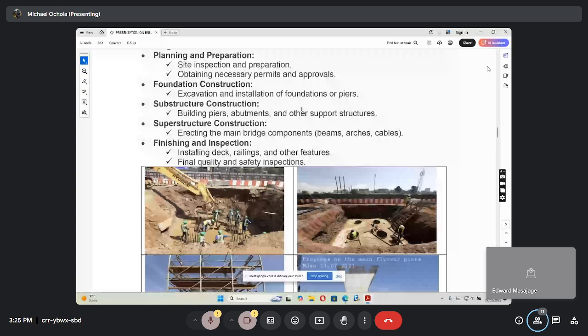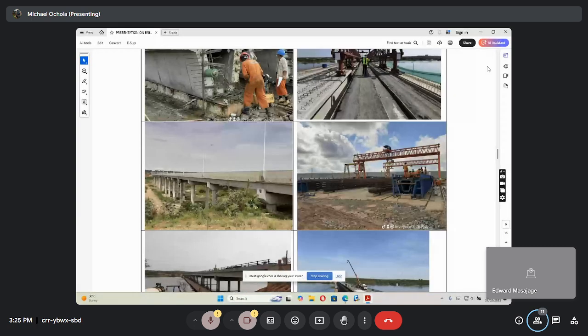So now we're going to look at pre-stressing. How does it work? In reinforced concrete you do ultimate limit state design, and you are not worried about serviceability, but in pre-stress, serviceability loading is important. This can create cracks, and cracks can initiate corrosion. So you must control all those things. So that's the benefit that we're going to get from the basics.